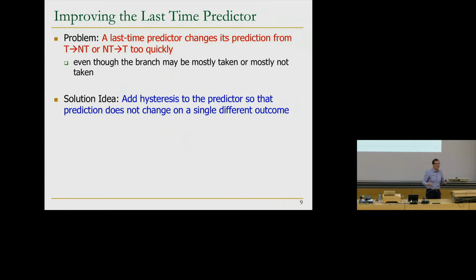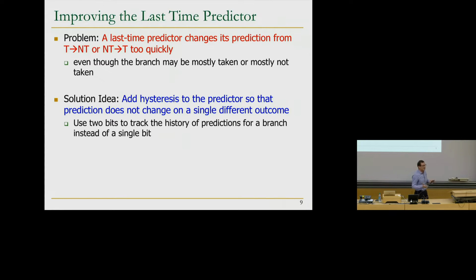That's true for the cooling as well, right? You don't quickly start cooling the room if you just see one piece of evidence that the temperature is increasing to 22.01. You wait until 22.8 degrees, for example. At that point, you say, okay, I have enough evidence that the temperature is really increasing, and now I'm going to go into cooling mode. So that's a very good example of hysteresis. And we want to do exactly the same thing in the systems that we build that make these sorts of decisions. So how do you actually add hysteresis into the system?